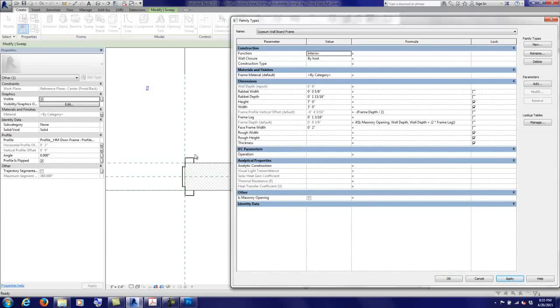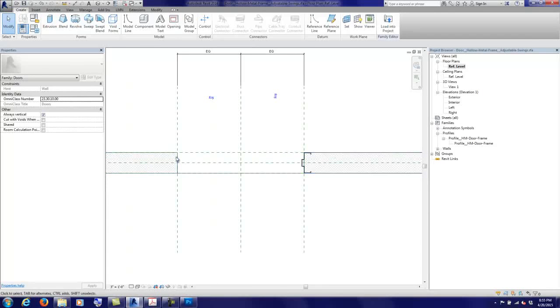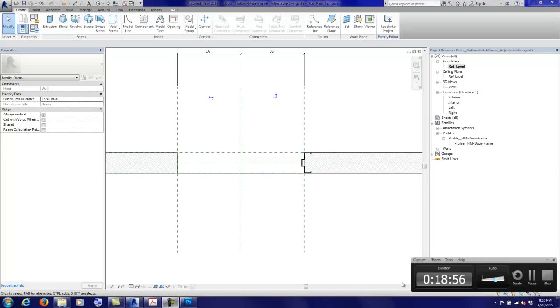So you can see there we can hit apply, which seems a little bit deep to me. Typically in our office we've always done everything 1/2 inch. But we'll keep it at that for now. I can change this now back to masonry, hit apply. You can see how that frame continuously keeps to change. Go ahead and hit save on that, and what we need to do is set up this frame on the other side, and then also at the head condition, and then join them together.